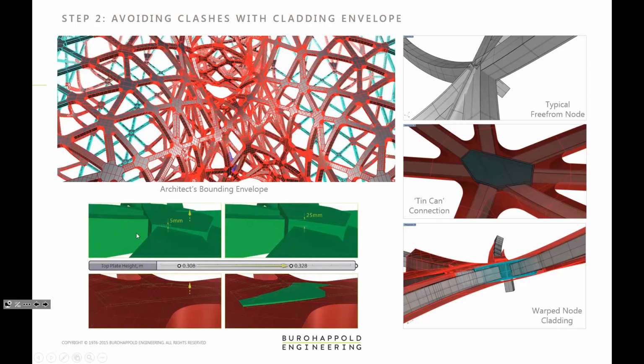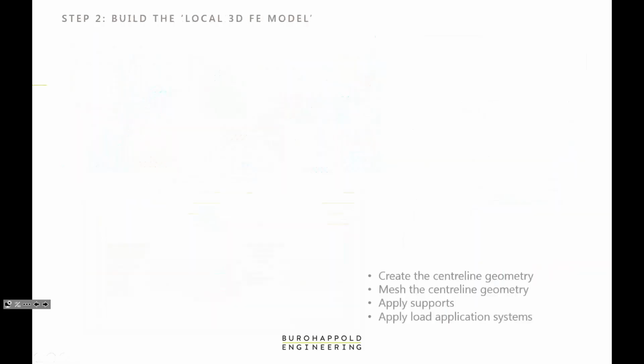We were able to develop a script where we could alter the depth of this node and look at whether or not it is poking out. Again, completely automated, because we couldn't afford to spend 2 weeks on a node. So with this particular tool, here at 25 mil depth from here to here, it pokes out. Reduce that to 5 mil, it doesn't poke out.